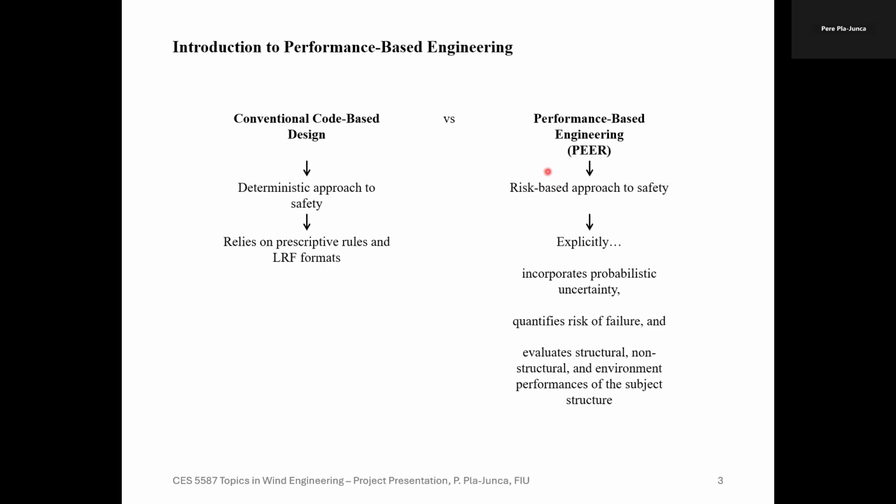So performance-based engineering is an analysis methodology that allows the designer to determine and know the performance of the structure under the design loads. Conventional code-based design approaches currently in place do not provide this information. So we design structures that we know are going to perform safely and adequately from a serviceability perspective, but we do not know the actual behavior of the structure under design loads. Performance-based engineering provides this information and also allows the designer to explicitly incorporate probabilistic uncertainty and explicitly quantify risk of failure.